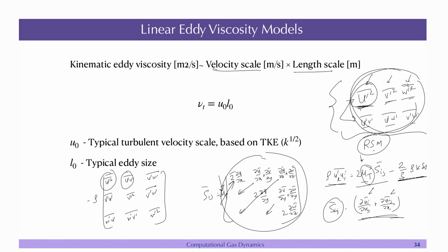So, one thing is that we are saying that my eddy viscosity is somehow similar to the kinematic viscosity that we have. Okay. That is the first argument. Secondly, it is much higher in the turbulent fluid than the kinematic viscosity, because as we discussed earlier, it leads to the mixing, right. So, how do we get this viscosity?